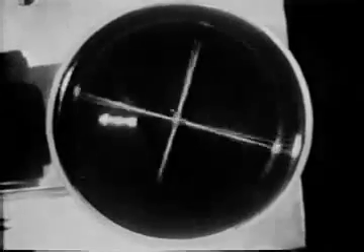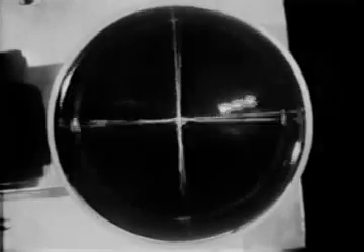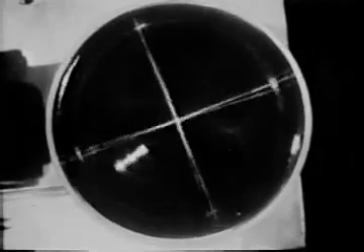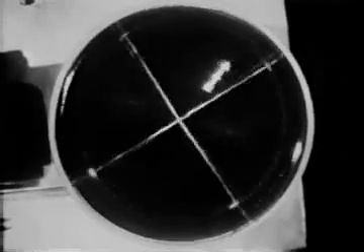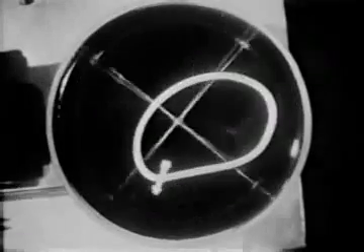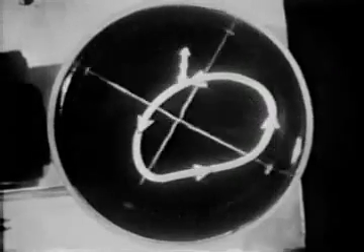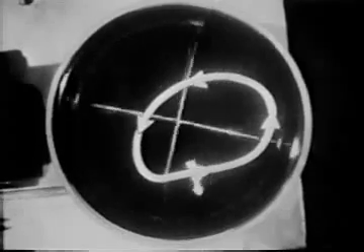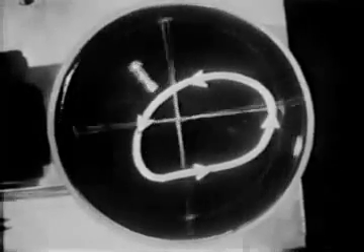The velocity varies inversely with radius. In the solid body rotation tank, the vertical vorticity is everywhere equal to twice the angular velocity of the tank. Every horizontal circuit you draw has a circulation equal to the flux of vertical vorticity through the area bounded by the circuit.